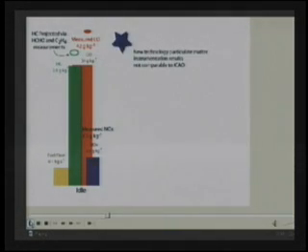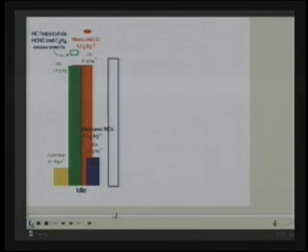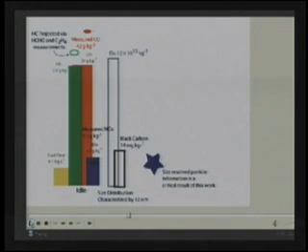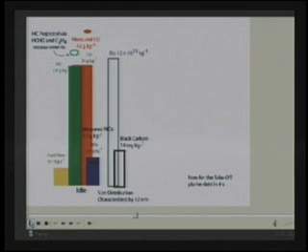And what we see, the bars are the certification, the dots are the measured data. We're a little low on NOx and a little high on CO and formaldehyde. That's not because of measurement error. That's because they weren't operating at the certification value. They were operating below that, at 4%. And you can see we have a low black carbon number on this chart and a high particle number count. If we look at takeoff, which we'll see coming up in just a moment,